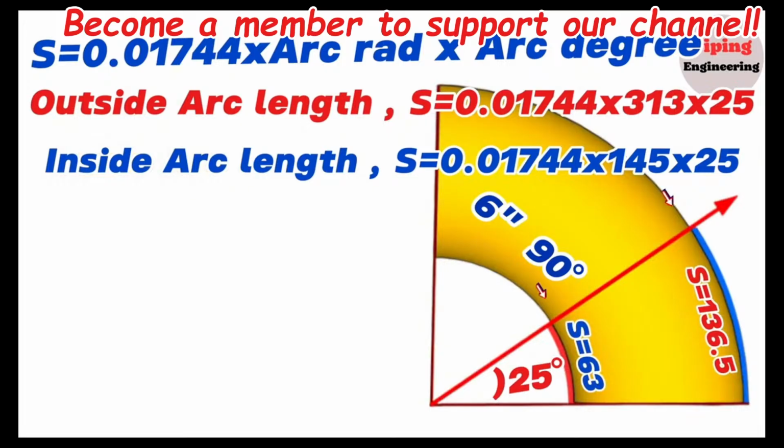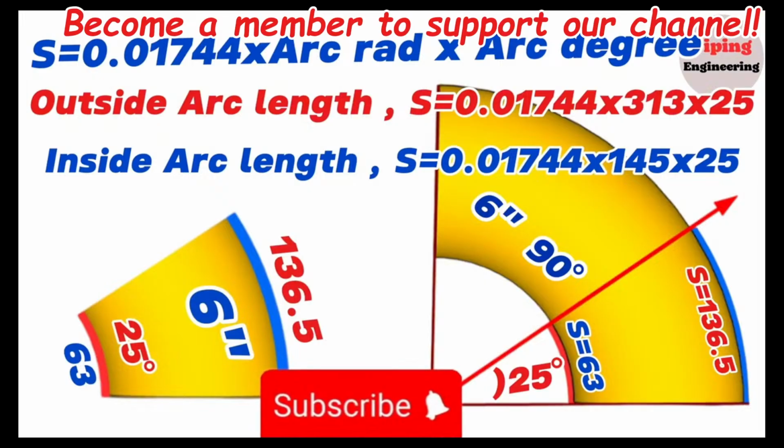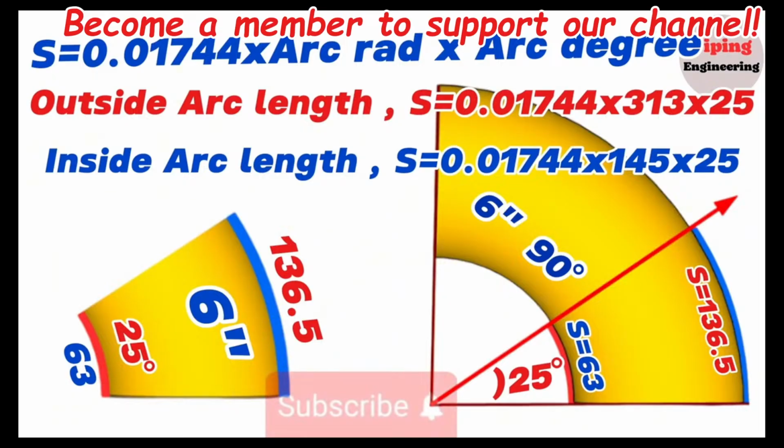Now we have 2 points on the 6-inch elbow. Connect these 2 points along the elbow. This line marked on the 6-inch elbow will be the cutting line of the 25-degree elbow, which will be cut from the 90-degree elbow. We saw that if we write the elbow degree and elbow radius to be cut in this formula, we can easily calculate and mark the outer and inner arc length of the desired elbow. By using this method, you can easily calculate arc length and cut any degree elbows.